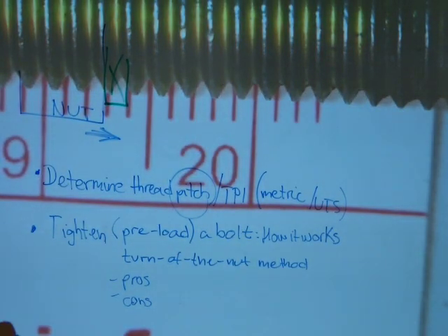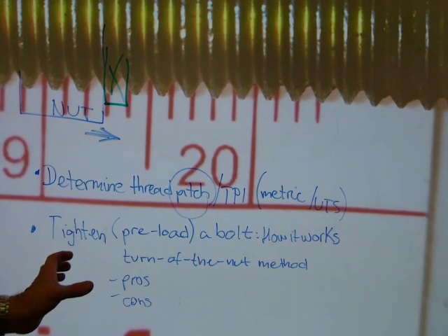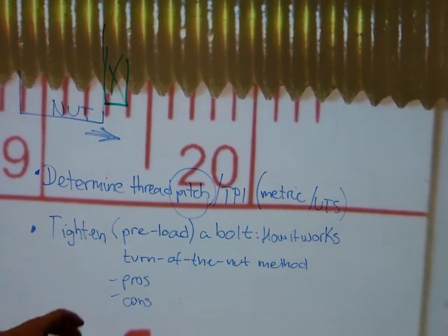That's what mechanical engineers are there for: they determine how many turns you should be taking with a nut, and it will only work for that size of nut in that particular application. Okay, so don't take it home and work on your car and eyeball the torque specification for any of your vehicles. For working on vehicles, have a torque wrench, please, a calibrated one.